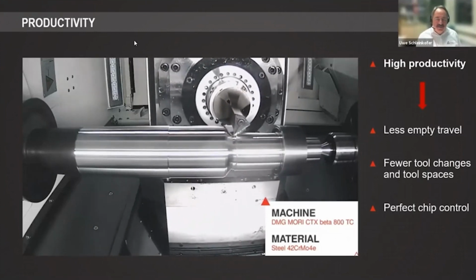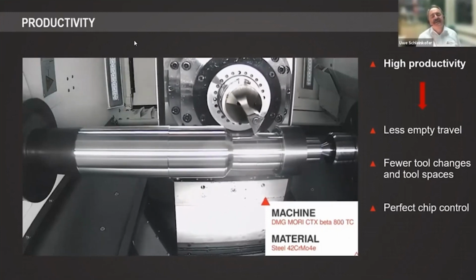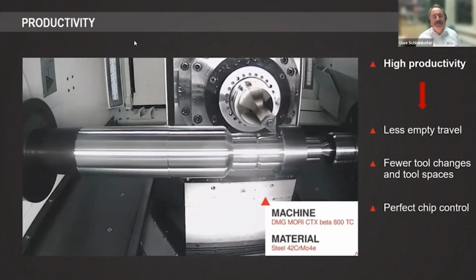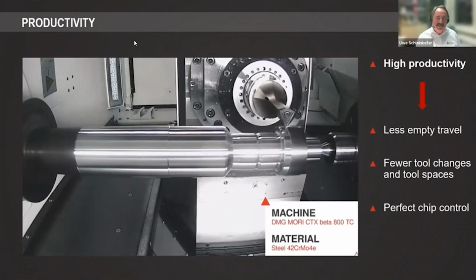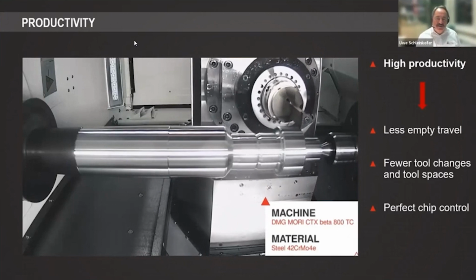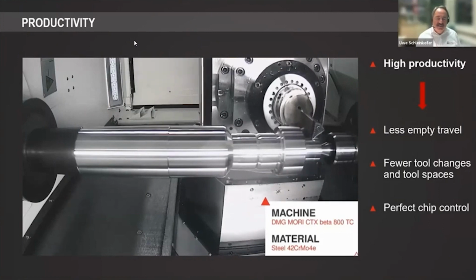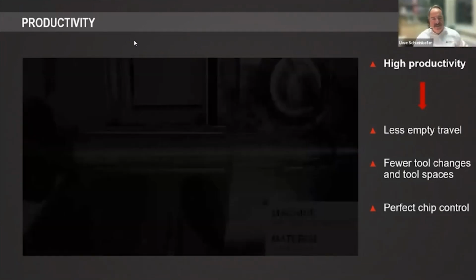So now we are going to the finishing, and we profile the surface. Now we're making a notch. Now we're moving further, going inside the 90 degrees. Now we're cleaning up the surface of this part. Now we're going down the finishing process, and now we are done. We could even do a groove in the notch in the back when we move the insert inside with the right approach angle.